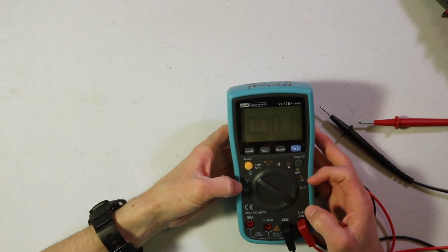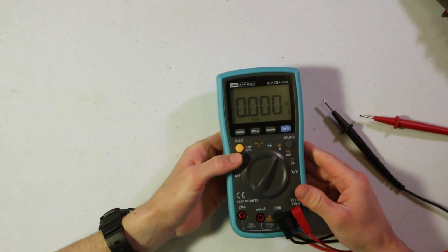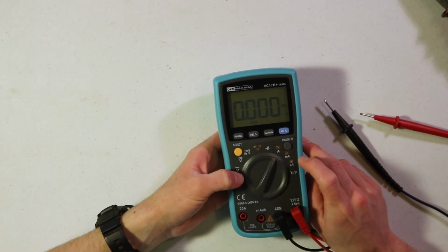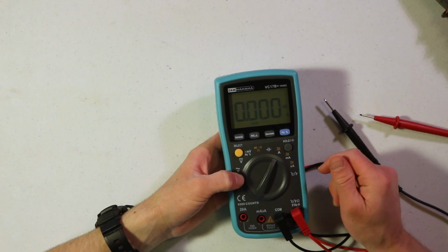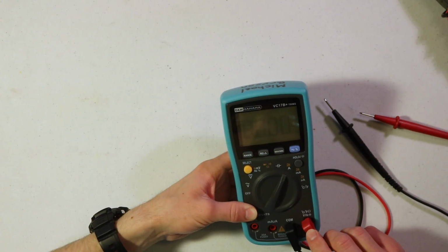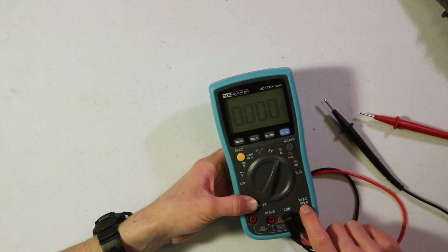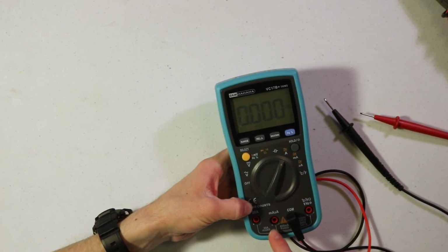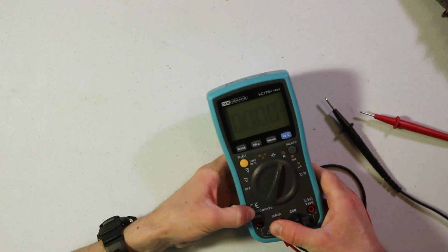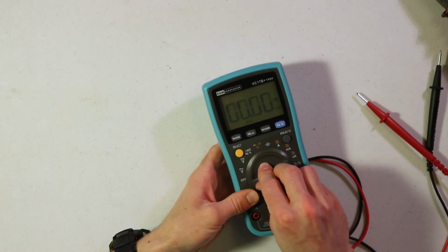The next thing to look at is going to be current. So for mine, I can turn this over here to current, and since current is measured in units of amps, then the A symbol here, or milliamps or microamps, are going to be the settings that you want to look for measuring current. And again, we want to make sure that the red probe is on the correct port. So right now, I want to unplug that. See, this one doesn't have current on here. So if I wanted to measure small currents, meaning milliamps or microamps, then I could plug this one in here, and then that would allow me to measure milliamps or microamps.